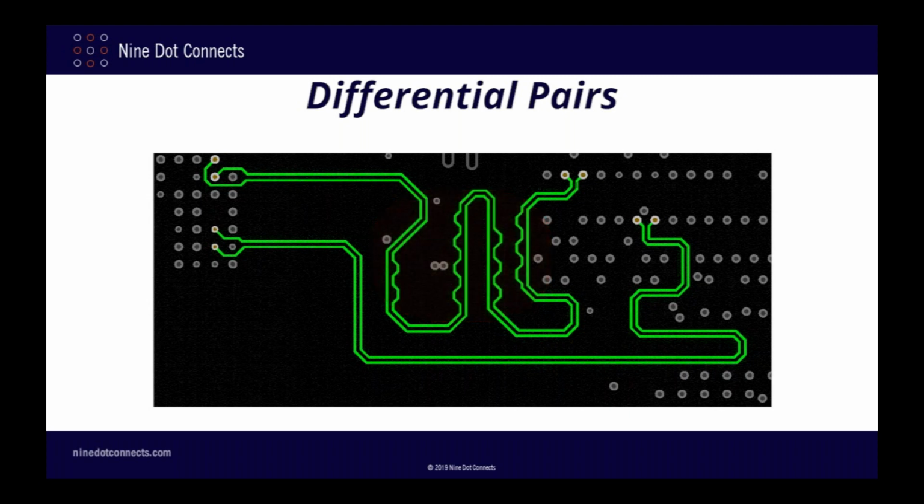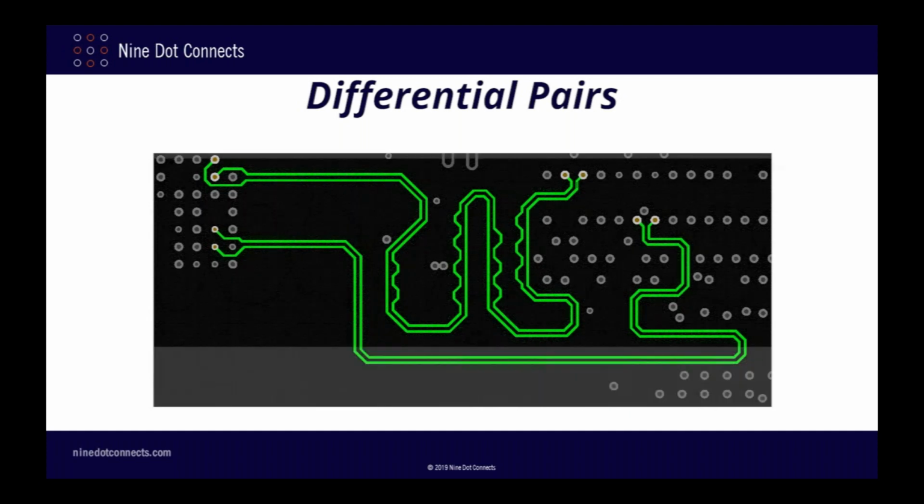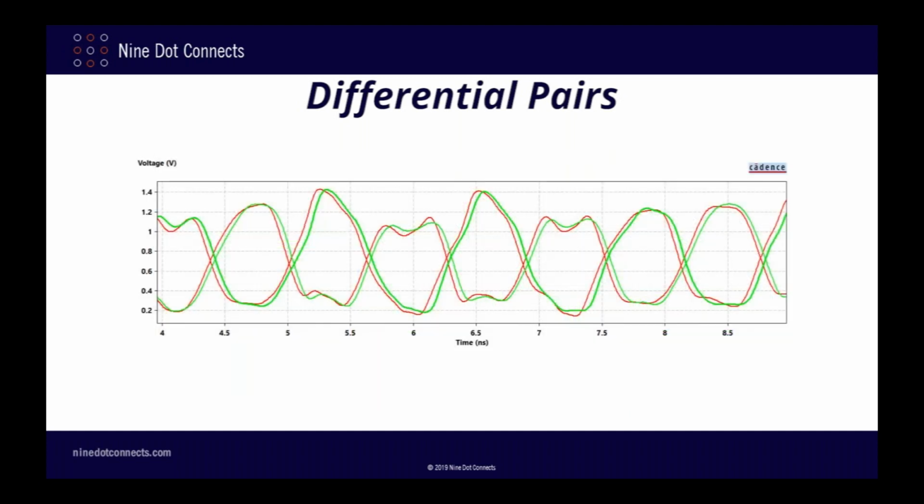As it turns out, there really isn't much of a problem with the final signal integrity. The wiggles do affect the higher frequency components and introduce some reflections, but these are minor enough not to affect the overall integrity of the signal. If we compare the time domain waveforms of both DQS0 and DQS1, we really don't see much difference. Here, the red trace is the clean DQS0 signal, and the green trace is the DQS1 with the length tuning wiggles. Other than some offset due to the fact that the overall lengths are different, the shapes of the waveforms are pretty similar, certainly nothing to cause any concern.